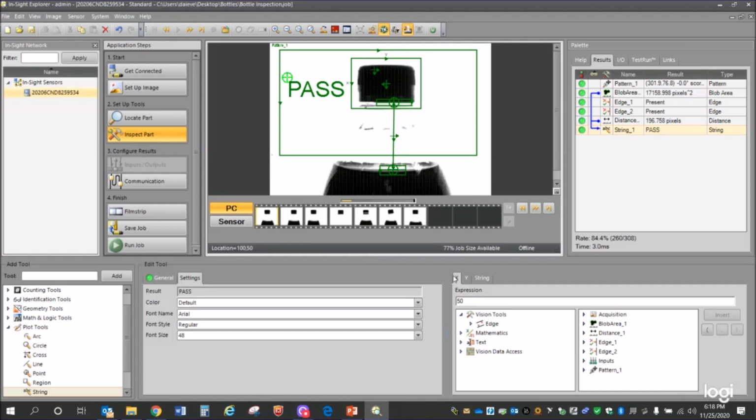So if you look at these robots, imagine all that plexiglass smoked out black and then lit from the inside. So we're not dependent on ambient light. We're lighting it up from the inside. And the other thing is the cameras have lights on them. We can flood that part with light as we're taking the image, get our good image, and then turn the light back off again. So that's the best way to go.